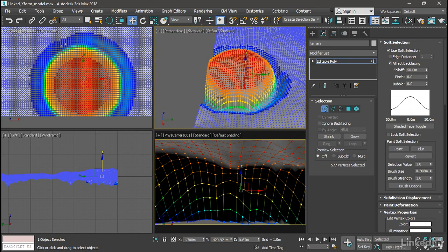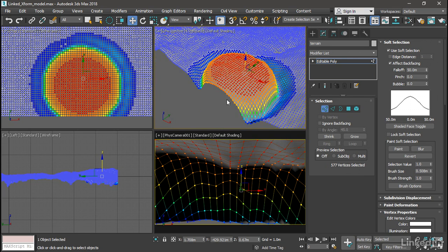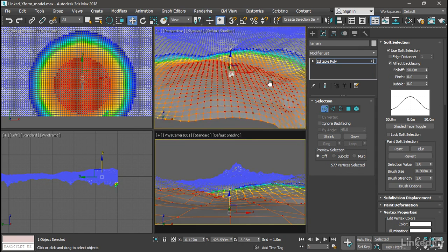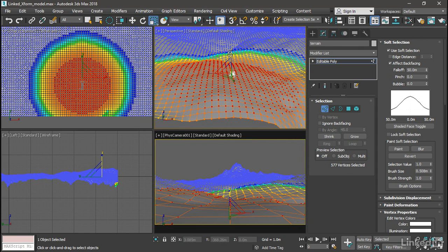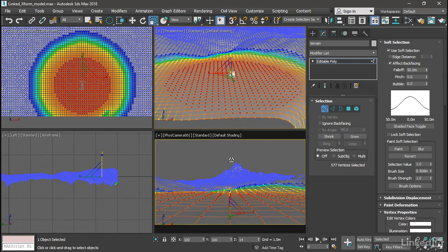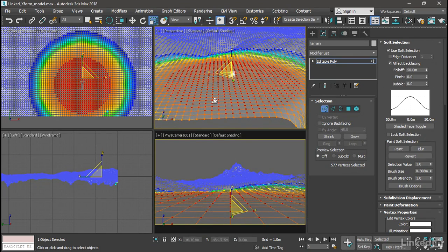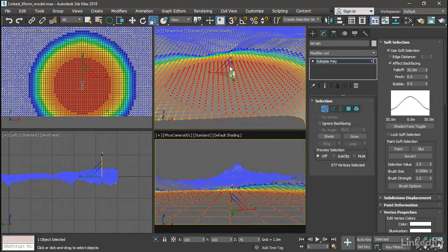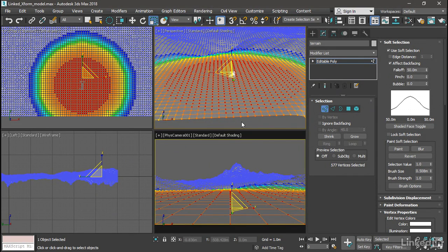And we've additionally got some issues here. So I'm going to undo those two movements with Control Z and show you also that if you want to try to scale, you'll have a similar issue. I'll choose the Scale tool and scale only in the Z axis to flatten that out. And eventually it will be perfectly flat once we have a scale of 0 there. And if I decide I want to scale those back up again, I won't be able to because I've destructively removed all of that scale information. It's always going to be more or less flat there in the center.